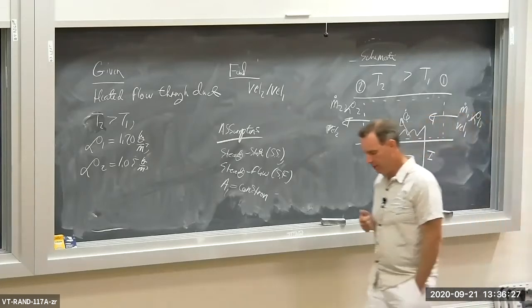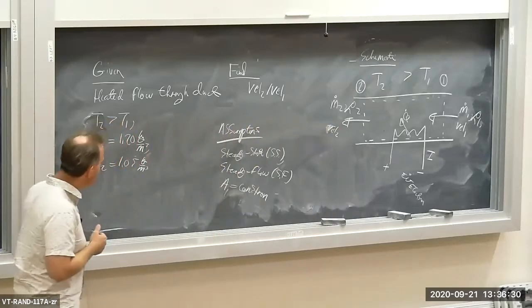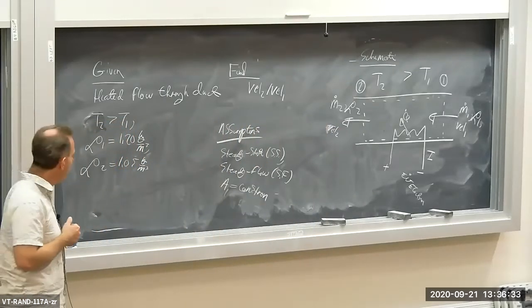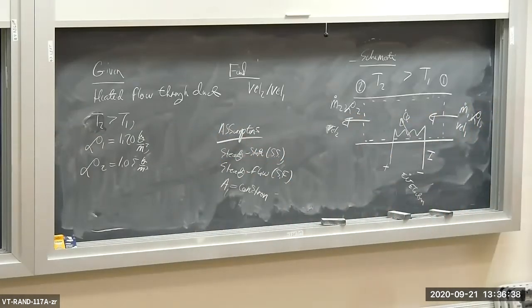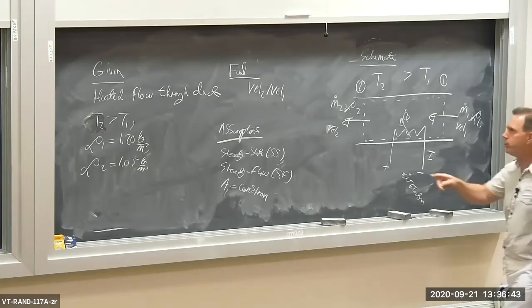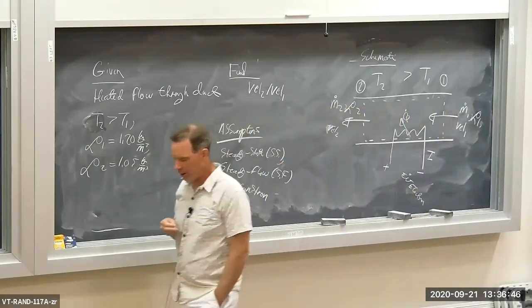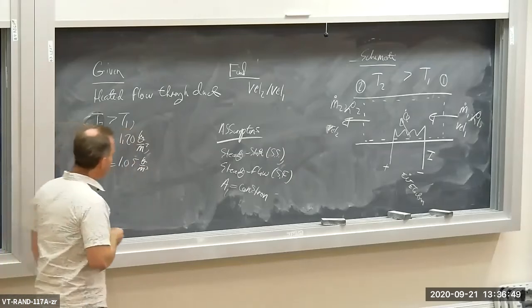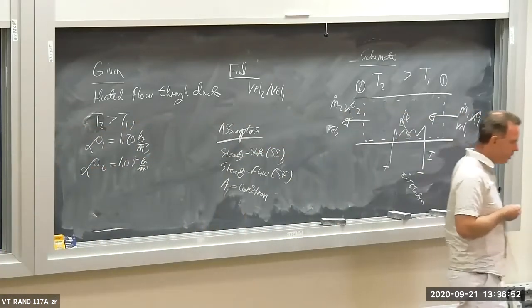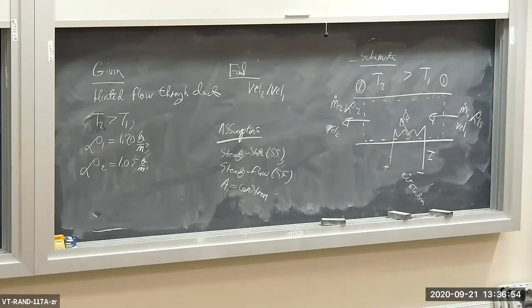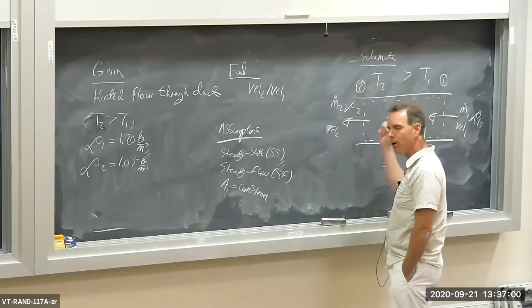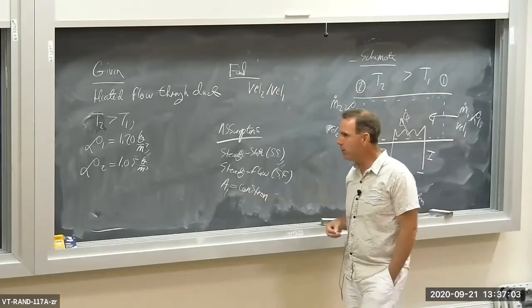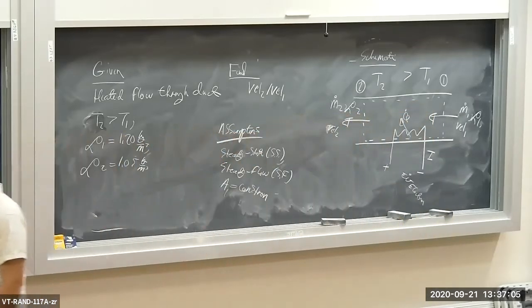Okay, so heated flow in a duct. T2 is greater than T1. Density falls as we go from the right to the left-hand side of the duct as it is heated. We're supposed to find the ratio of the outlet to the inlet velocity, VEL2 divided by VEL1. That's what we're supposed to find. Now, assumptions here. I'm going to assume everything is constant in time, steady flow, steady state. And I'm also going to assume that the flow area, or the area of the duct, is constant. So A is equal to a constant. So those are my assumptions in this problem.